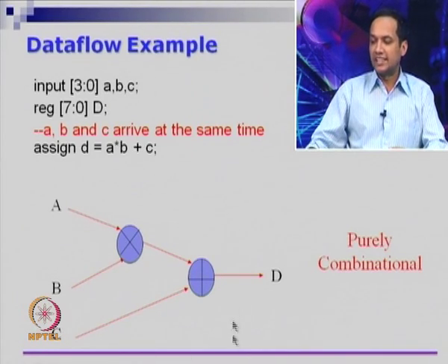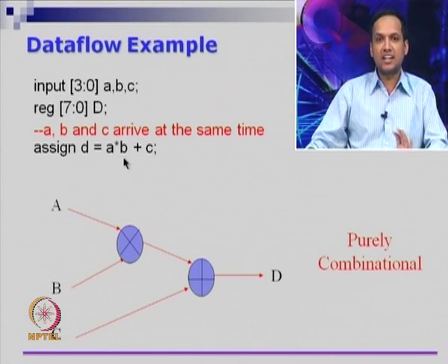You could infer something like this by writing a line of code like this. So you could also go and write this whole thing in a structural manner. By that, for the adder you may actually use a ripple carry adder, for a multiplier you may come up with your own way of doing multiplication of two numbers and so on. But if you do that, the programmer's intent is buried inside lots of lines of code, whereas this is very clean and many tools can immediately understand that you are looking for multiplication and addition.